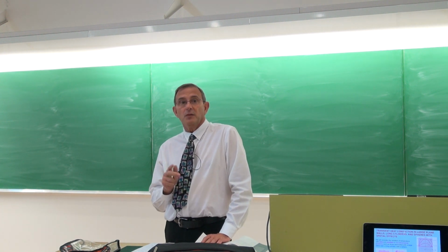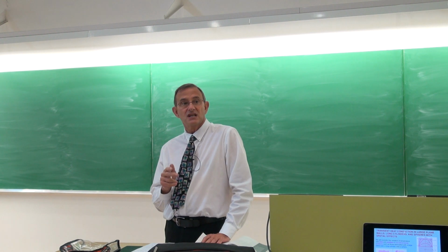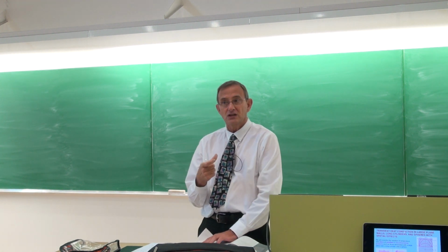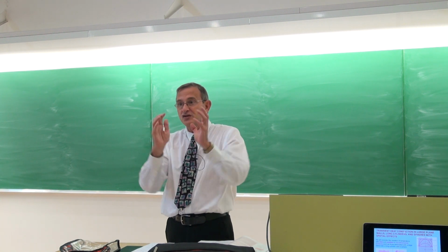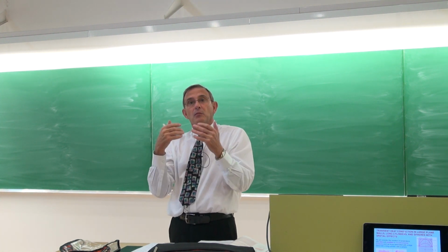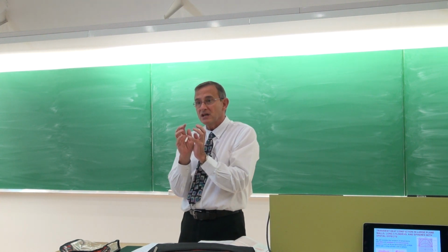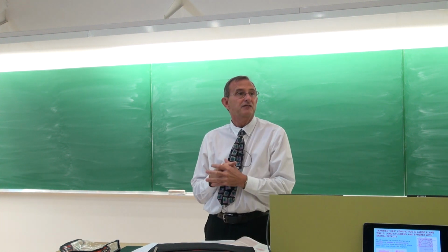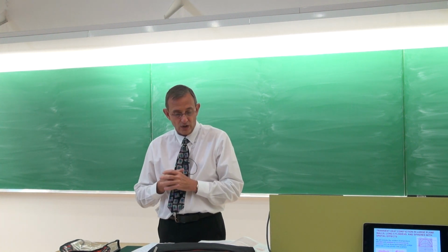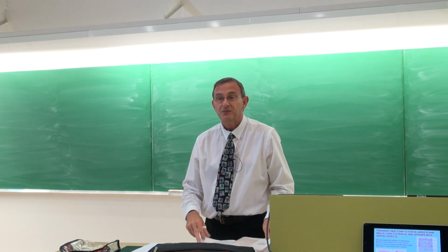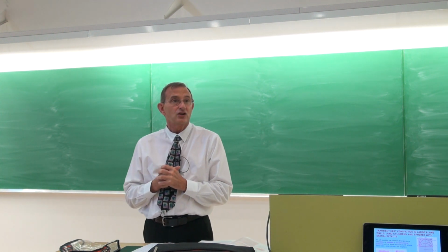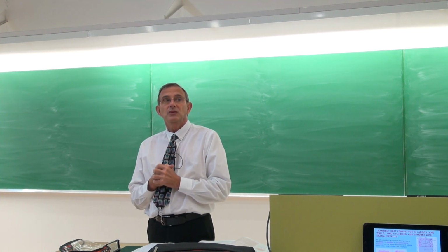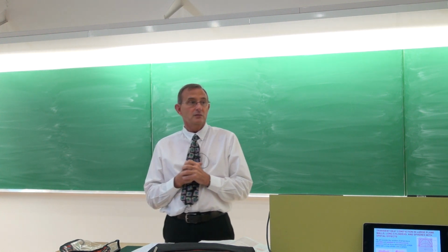And that is being prescribed by the Biot number. The Biot number gives us the ratio of the conduction resistance divided by the convection resistance. The convection is on the surface and it wants to go in, but how quickly it can go in is being determined by the resistance of the body itself. And if the Biot number is smaller than 0.1, then normally you will get a good approximation. Something else that was very important there is in the calculation of the Biot number, the characteristic length, that it can be calculated by using the volume divided by the surface area.